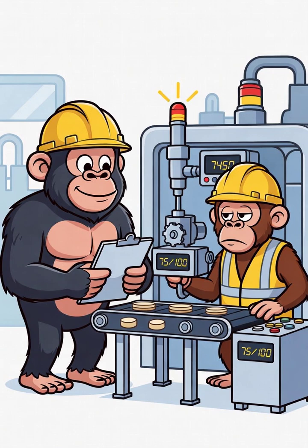When Gary investigates, he finds several culprits. First, the photo sensor that detects incoming parts is dirty, so it's causing micro stops. Second, the lubricant in the machine is old, so the mechanism is running slightly slower than it should. Third, Milo adjusted the speed down to 90% because he noticed the parts were getting slightly scratched at full speed. He was trying to help, but it's still a performance loss. None of these issues stopped the machine completely, but they're killing productivity.